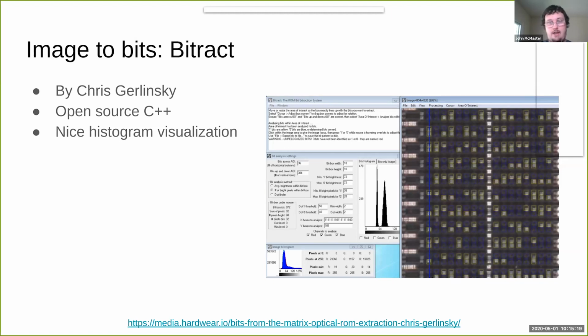your image. So in this example image, you can see 2 histogram peaks. And that basically means that one of those is probably the 1 and one of them is a 0. So if you set some thresholds within those histogram values, you should probably correctly classify most of the bits in your image.